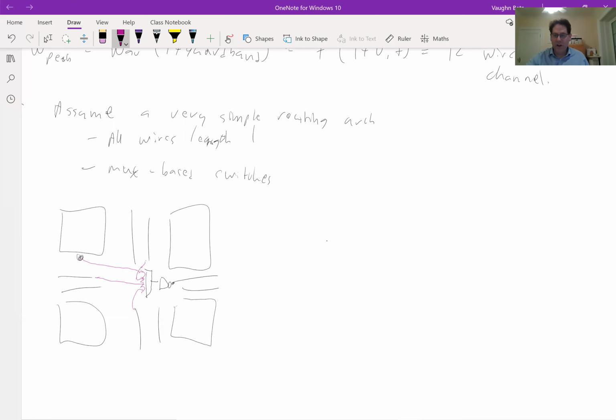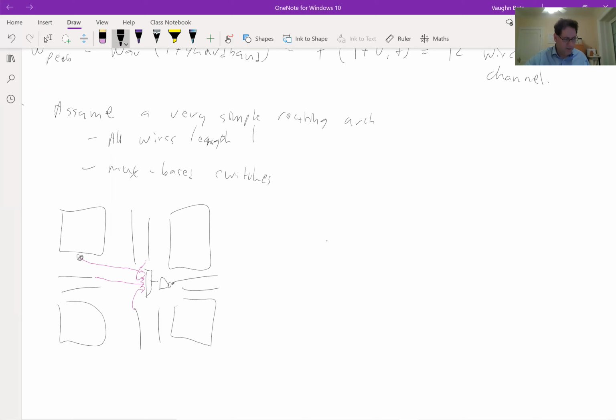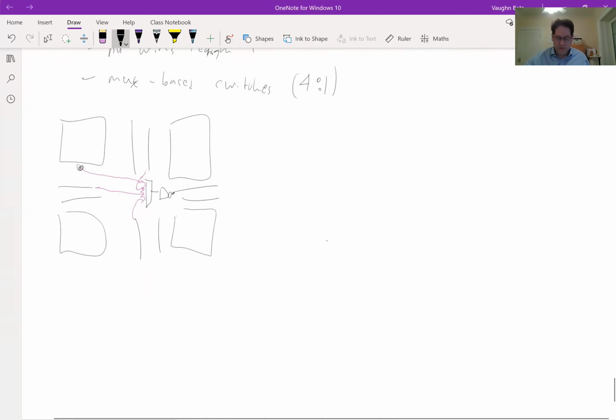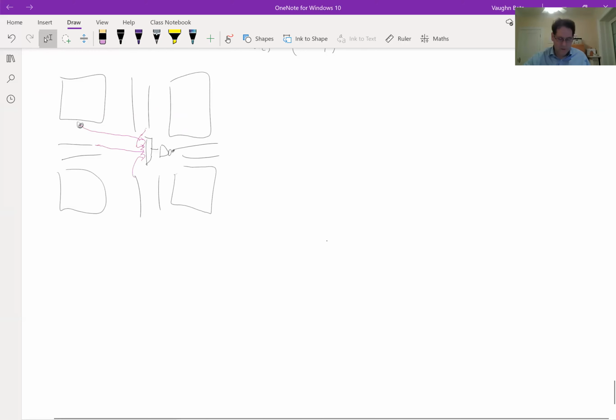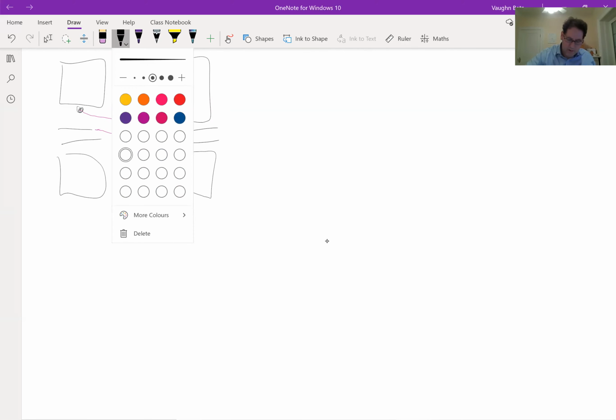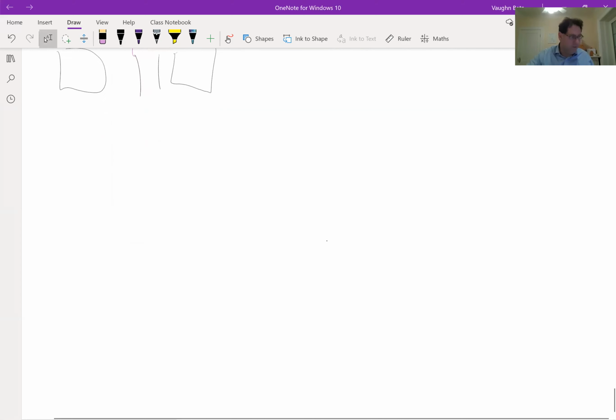It's not obvious that this is enough flexibility, but if I don't have at least this much, it's probably going to be very hard to route. And we'll look at some analyses of switch patterns later. But this is a fairly constrained, but not crazy switch pattern. So with this one, I need a 4-to-1 mux. Okay, because if I repeat this kind of pattern for every one of these routing wires, every one of these routing wires is going to get a mux, and each of those muxes is going to have 4 wires that feed into it. Does that make sense? Okay, let me put in this. This is my LUT. Okay, so let's work out this area.